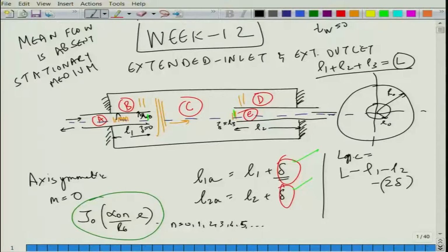But again, like I said, this analytical thing is only suitable or amenable to analytical solution if the ports are concentric, because at r is equal to r naught, you have the condition del r of p is 0, and this is also true for r is equal to capital R naught, and the radial velocity is also 0. So, the idea is that we can find a set of orthogonal functions for such a thing.